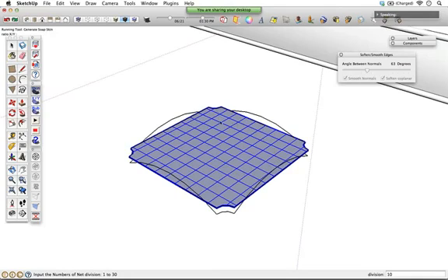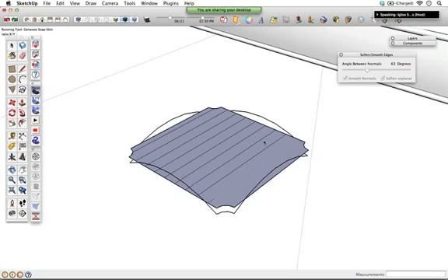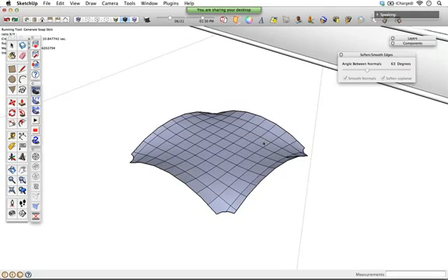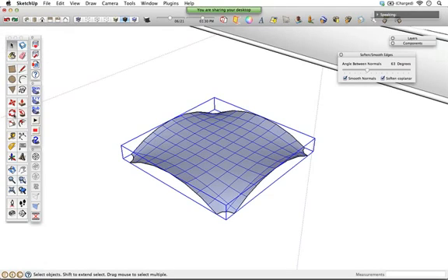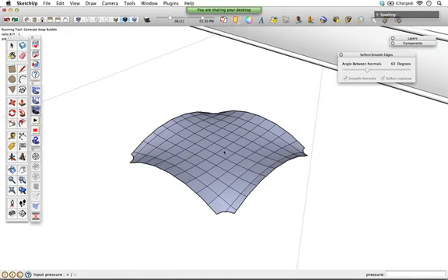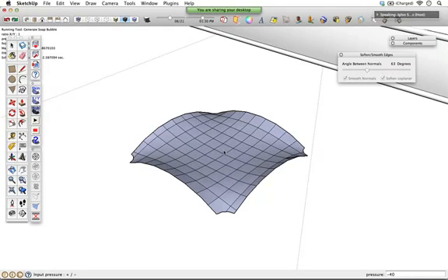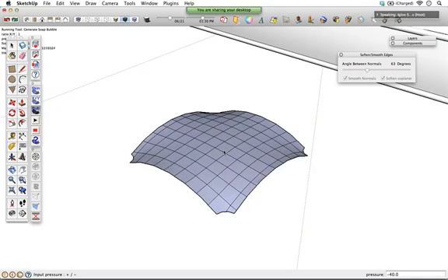So you can see here, this is basically a 10 by 10 grid. If I'm cool with that, press enter, and the Soap Skin & Bubble does its thing, gets that all to fill in. And then once it's filled in, I can pick that surface and inflate it with a pressure of around -40 or -60.